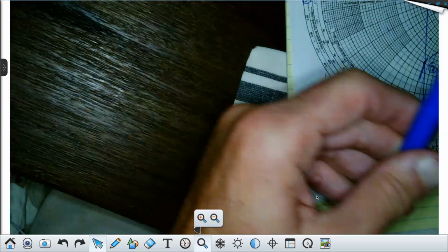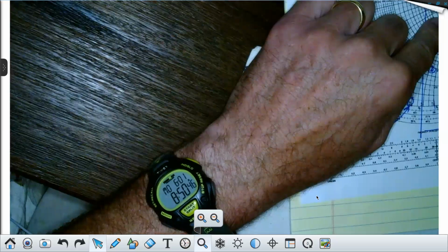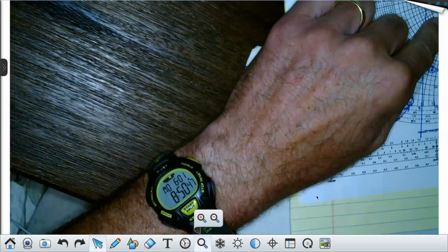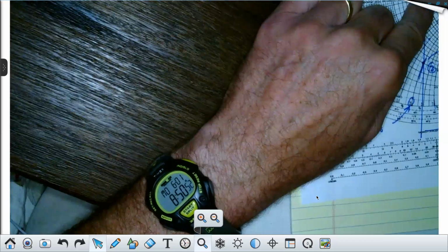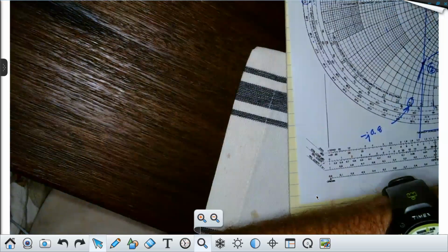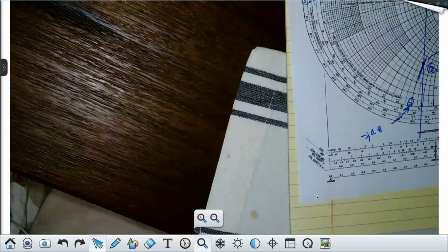About 4.4. And that point is the standing wave ratio. Right where it crosses the equator, these are circles of constant reflection coefficient magnitude, but the actual angle changes. When it crosses this point, you get the standing wave ratio. And it happens to be also something that's strictly real. There's no imaginary part. So the input impedance would be Z naught times the standing wave ratio at this point.